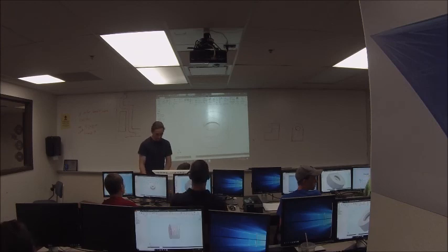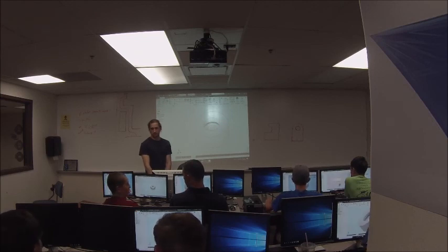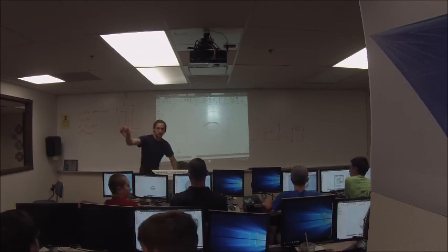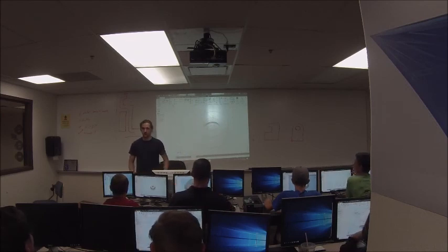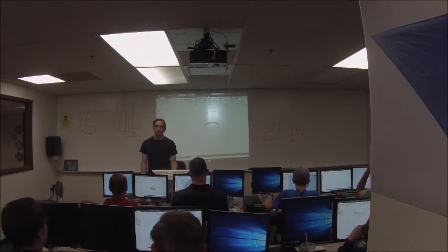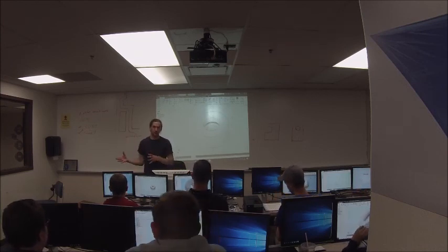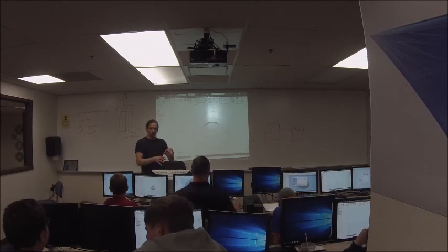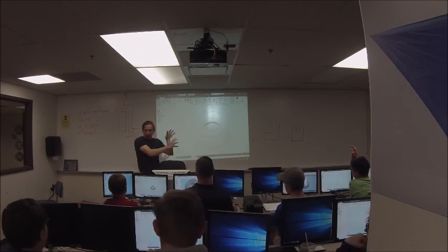Hey Ryan, are there pre-made parts or models for motors and stuff that you can download? If you go to VEX, yes. McMaster-Carr also has models. The thing is, they're not Inventor models. They're what are called STEP files, which is a kind of universal 3D CAD format. When you import it, you're just going to get kind of a lump. It's going to look right, but you're not going to have features like extrude and revolve.